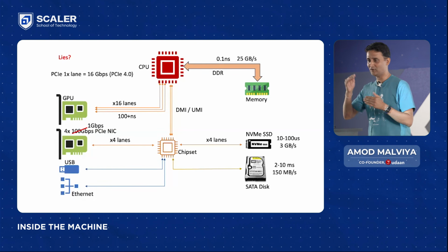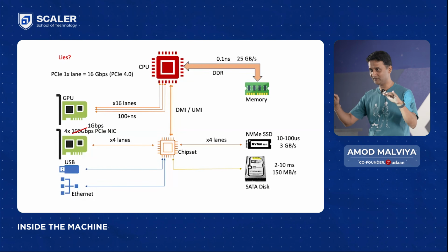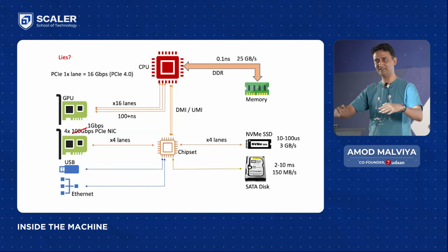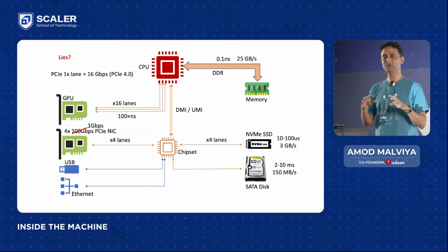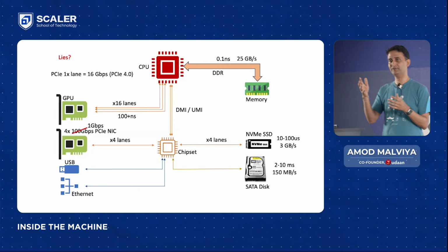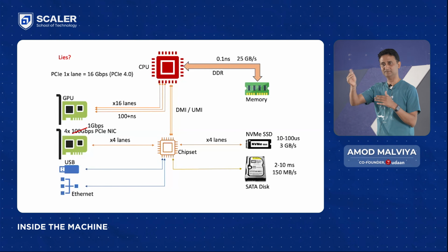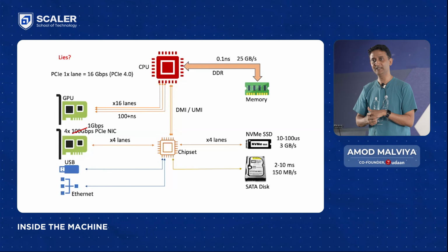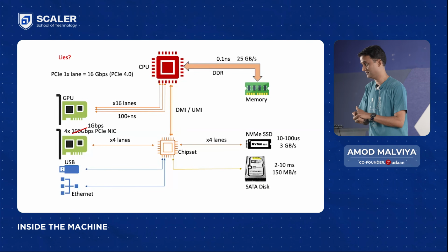Speed of signaling on a wire on a PCB substrate. Okay, that hard surface that you actually see. Let's assume that the speed of electrical signaling is half of the speed of light. Okay, it varies a little depending upon the PCB substrate. But if it is half, it means that it is 1.5 times 10 to the power 8 meters per second, right?